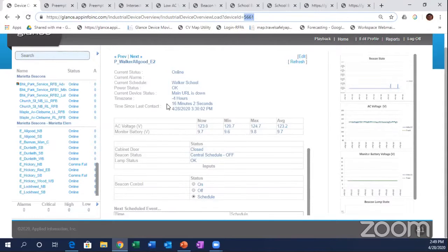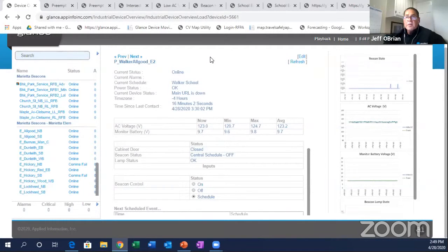Thanks. Awesome. Okay, so this question is regarding some of the statuses that we're showing in some of the reports you guys were sharing with us. And it says, what does no SPAT mean under network status? Can you explain what would contribute to those statuses? Yeah, Chris, you want to take that or you want me to do it? Yeah, no SPAT. The traffic controller has the ability to put out signal phase and timing data, and we use that for connected vehicle applications. So all that is showing you is whether that controller is currently sending that information to our device for us to read, or it's not sending that information.